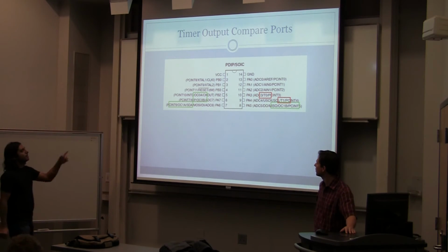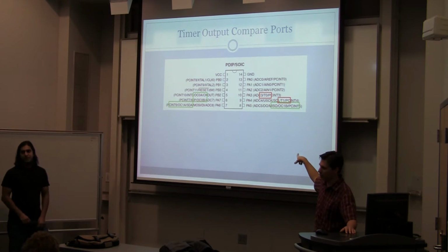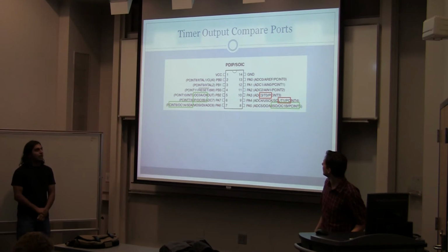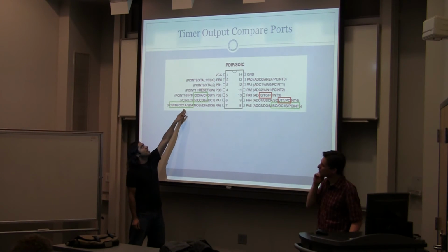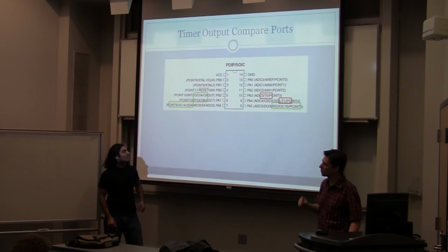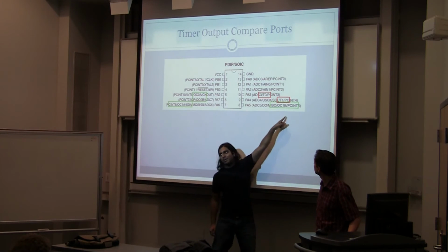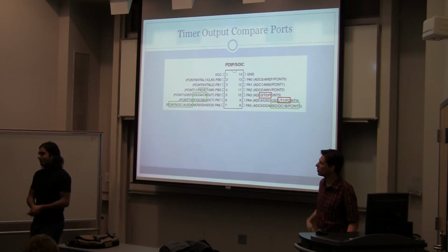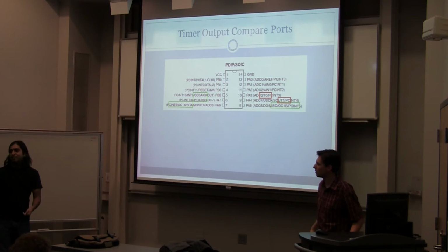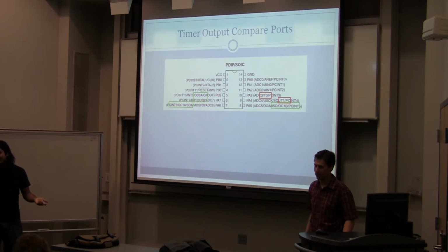Yeah, these output compare pins can. So the ones in green, yes. Keep in mind that they're tied to a particular timer. So if you're doing PWM on 1, that means your OC1B is also stuck with that same timer at whatever frequency. You can use the pin normally, but you couldn't have a different PWM running.